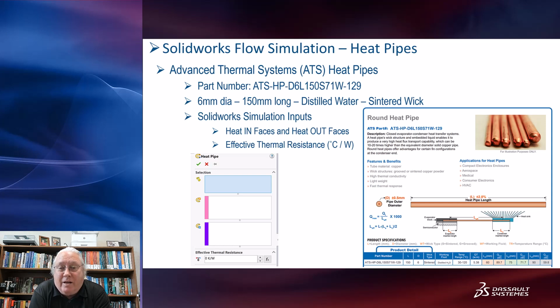It's under a vacuum, so the boiling point of water under a vacuum is very, very low, which means it doesn't take that high of a temperature on the left side, the hot side, where you're trying to extract the heat. You heat that up, it heats up that water, and it boils well below 212 degrees, 100 degrees centigrade, because it's under a vacuum.